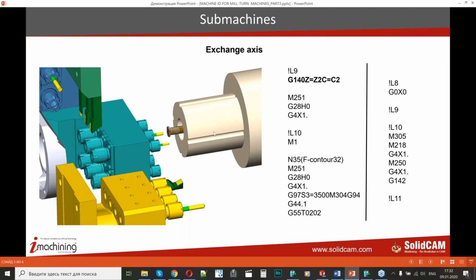This machine needs an axis exchange procedure to provide back tool post operations. There is a special G140 code. You can see it here, G140, which lets the first channel operate with axes from the second channel.